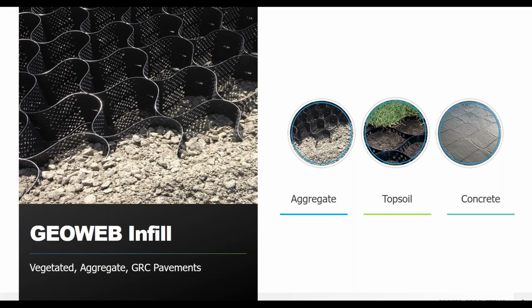So if you want to have a clean washed stone, then the cells can provide confinement and aid in compaction of those cohesionless soils. It provides an apparent cohesion to the system. And without those fines, you can significantly improve the drainage and let the water flow from the surface down through the system freely, preventing pore pressure buildup and global failure of the cross section.